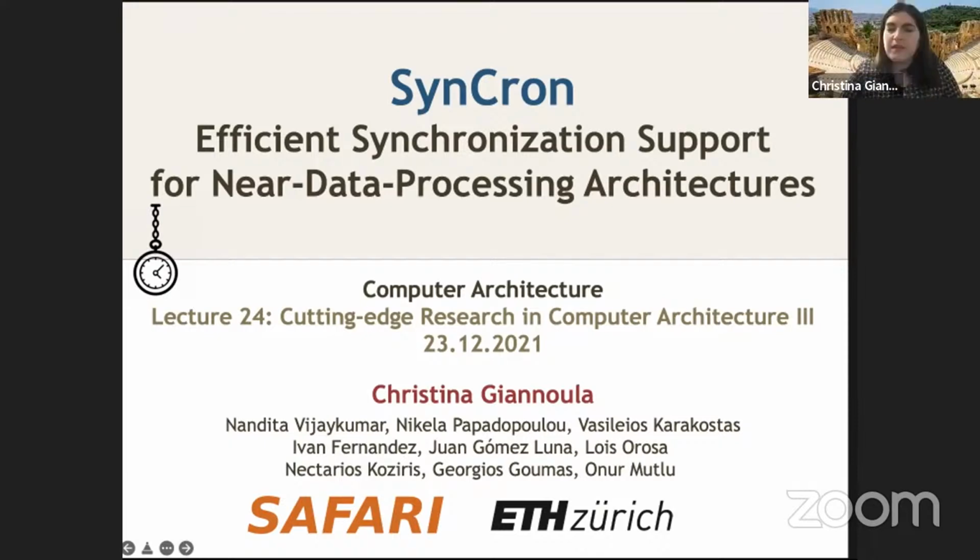Yes. So there is a trade-off there, because if you design the synchronization table to be very, very large, and you never overflow, the cost of the synchronization table is higher because you have a higher on-chip cache memory that you need to access, and the latency is higher. If you design the synchronization table to be small enough in order to have a very low latency cost, you overflow very frequently and you need to go to main memory. So you have to tune this somehow.